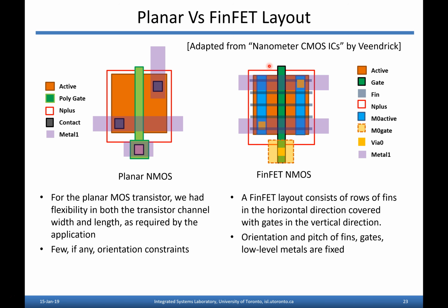So here's a typical FinFET transistor layout view. You've got the gate running vertically here in green, but the channel width is divided into these individual fins that are pictured here. Each of those lines is one fin. And those fins have to appear on a fixed pitch that's defined by the technology. You can't set the spacing of them to whatever you want. They run at a constant pitch across the whole chip effectively.